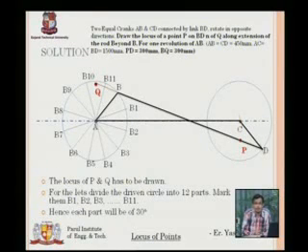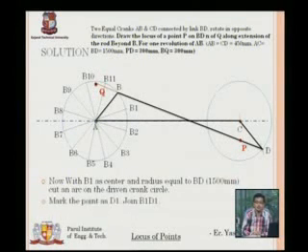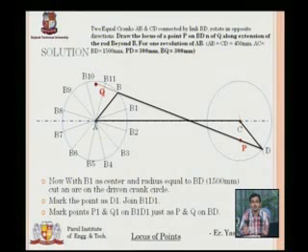So now again what I want to do, say I'll take AB1. Now I want to find the position of the driven crank according to my driving crank's position AB1. So again, the same thing that we did, the radius will be taken equal to the connecting rod in all cases. The link which is moving, which is connecting both the driven and the driving, will always be taken. So I will take radius equal to BD first. Now I'll decide the center. The center is going to be B1, and I'm going to cut an arc on the circle with center C like this, D1.